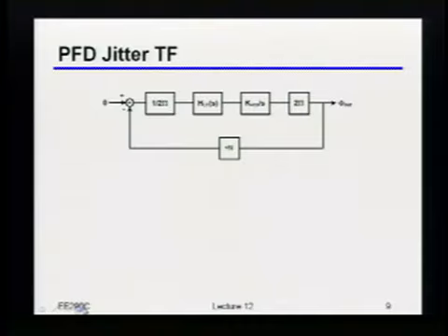After the 1/2 pi. Okay, yeah. So there's one of two places I could do it. I could either do it after the 1/2 pi, or since I'm still probably working in the phase domain, I'll add it in front of the 1/2 pi, right? So there's just some T jitter due to the PFD, okay? So now the hopefully very obvious question, but just to make sure it's clear: what would be the transfer function that PFD jitter would experience?